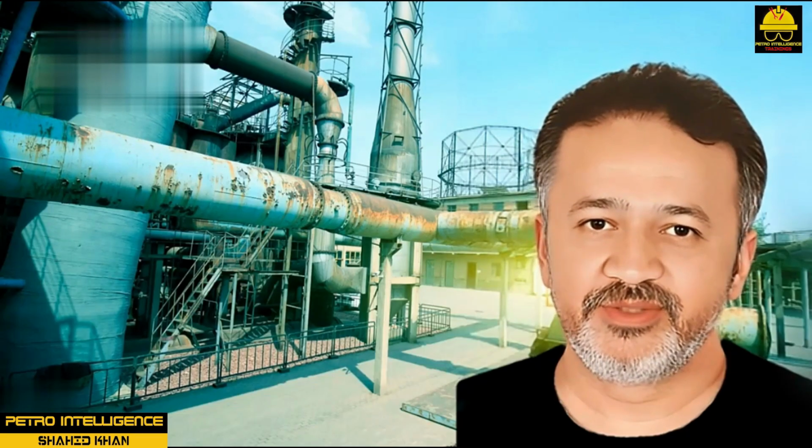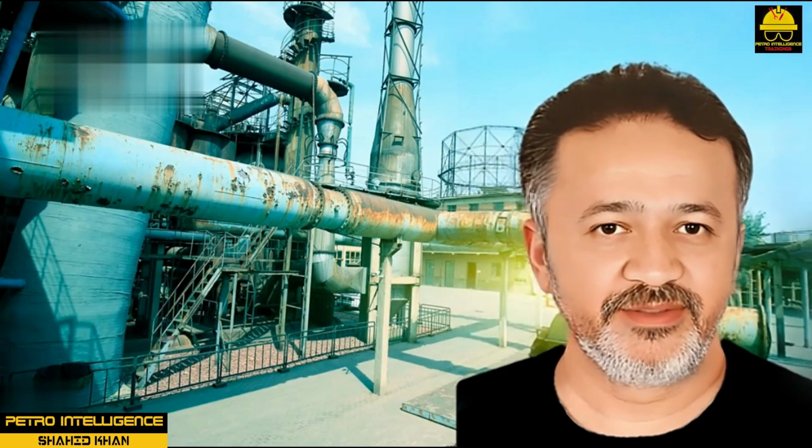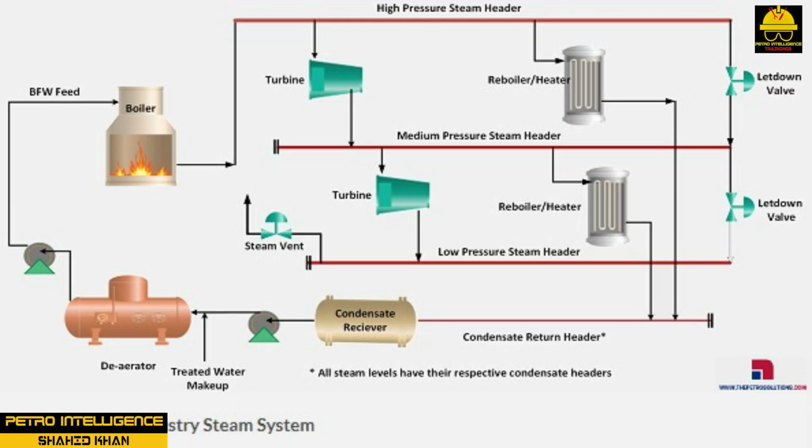Low-pressure steam, 50 to 60 psig. LP steam is supplied by lowering the pressure from the MP header, or by extraction from a steam turbine continuous blowdown drum. Nominal steam pressure in the low-pressure header is 50 psig. Steam to the LP steam header may be supplied from the exhaust of steam turbine-driven pumps.